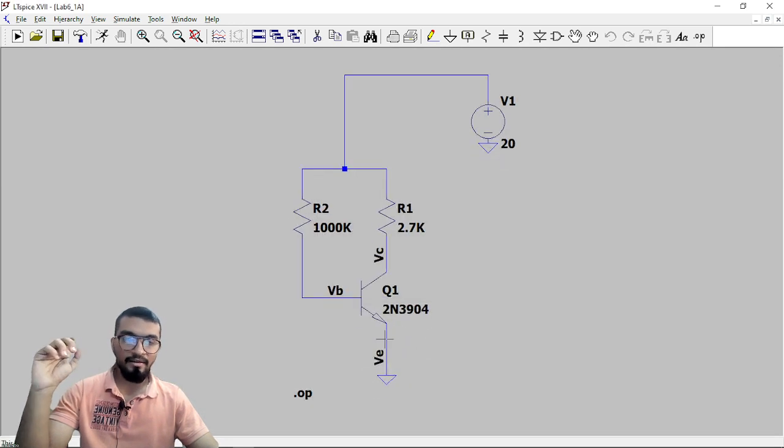So basically this is 0 voltage. The VB voltage of this 2N3904, or the cutoff voltage, you can calculate. You will have the fixed value here, so that value will be given here. So 0 plus the cutoff voltage value of this 2N3904 will be the VB value, and it will be constant. Now because you have this voltage available and this voltage available, you will be able to calculate IB, and you have beta, so you will be able to calculate IC.